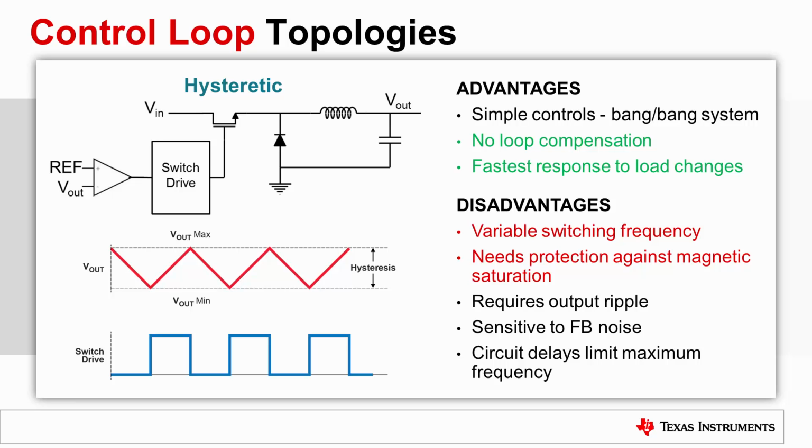In summary, hysteretic control is a fine choice for power supplies that value ease of use and need extremely fast transient response. Care should be taken to understand the implications of a quasi-fixed frequency operation and its effects on the system downstream.